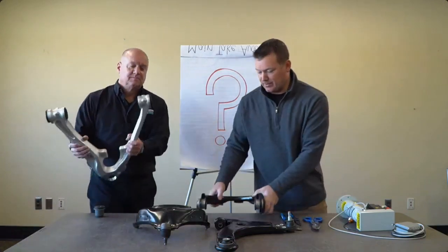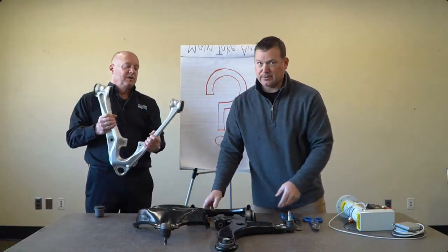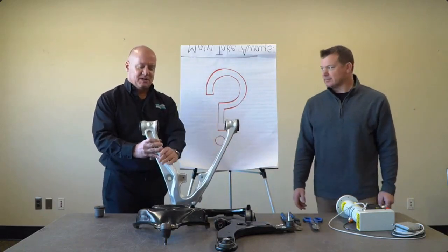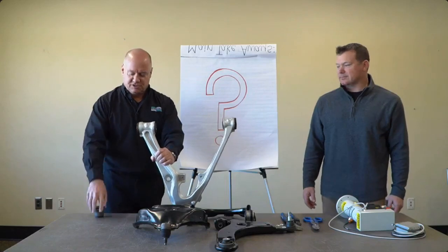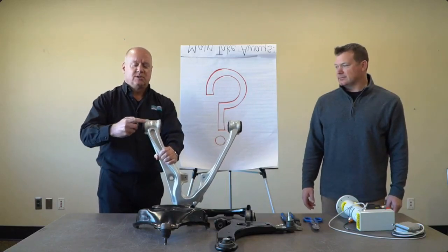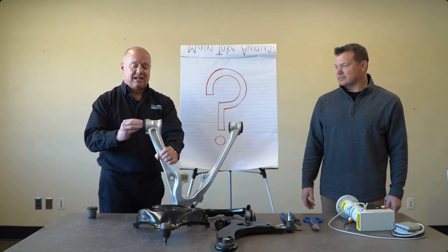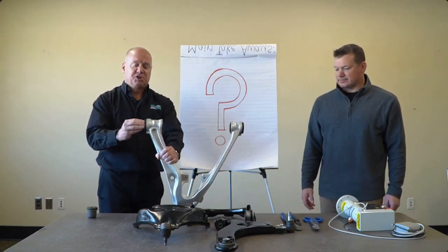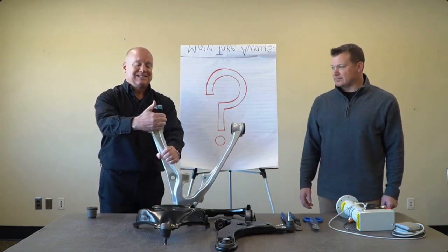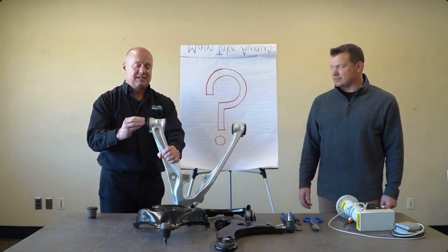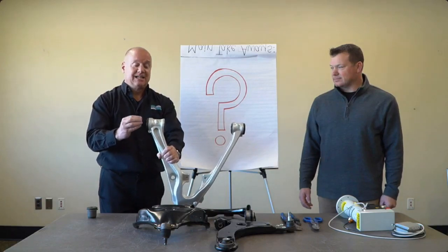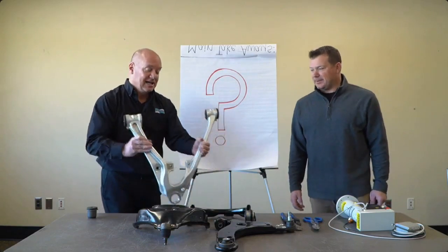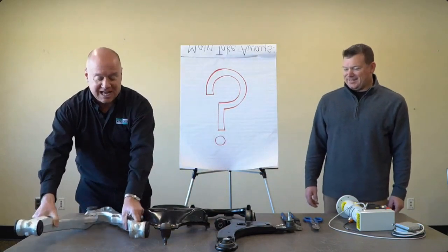And that's one of the methods or techniques we use for that. We didn't talk about this part, just for time, but these bushings also don't have an outside can. It's only rubber. And these you have to kind of bounce into place. You hit them to a depth, you back off. You hit them short on purpose, back off, see how much you've missed, and you bounce them in. Sometimes it'll take 3 or 4 or 5 hits to nudge it into place, because these are very hard to put into place accurately. But we've learned over the years how to do it quite well.